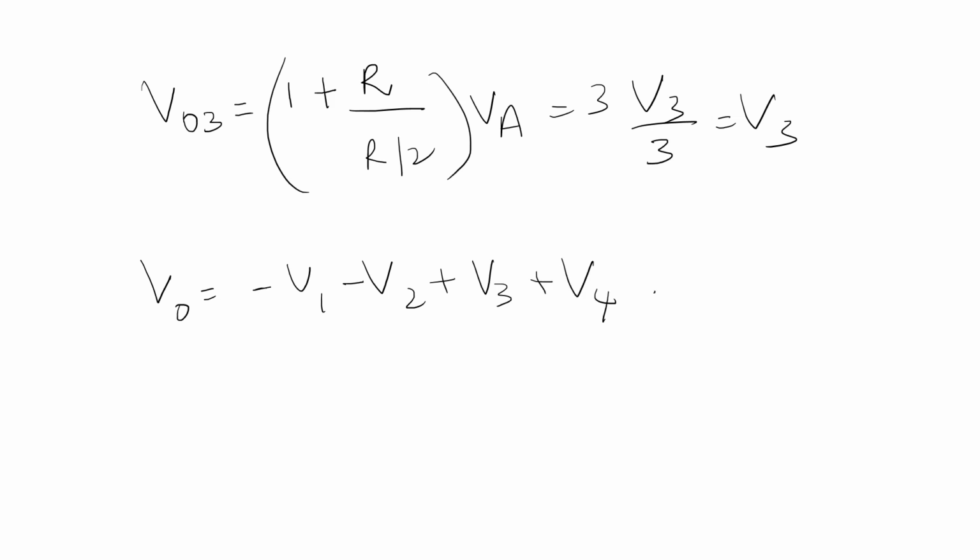And the other component is the op amp also acting as a scaling adder. Scaling adder. A different weight can be assigned to each input of a summing amplifier by simply adjusting the values of the input resistors.